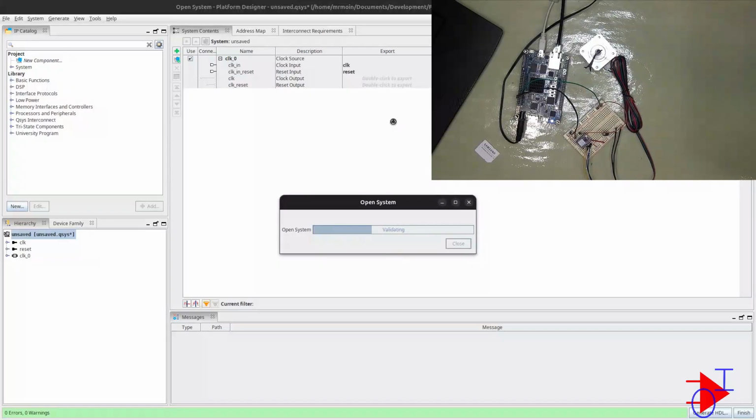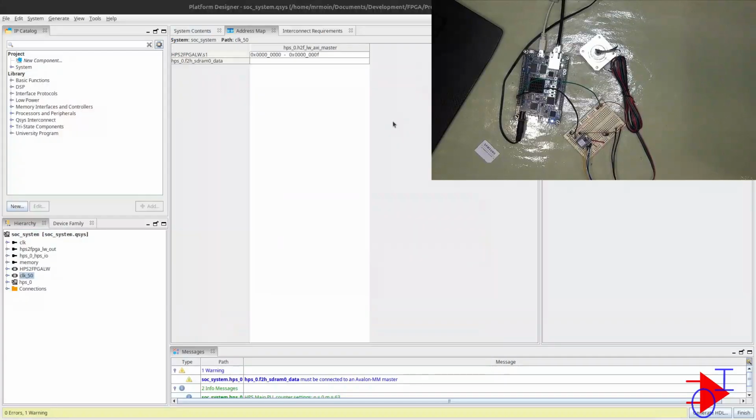In our case right now, the FPGA side is just reading from that memory location, and it's just one memory location at this time. So the place where the HPS is going to write to is going to be 0, the very initial address of the memory location.